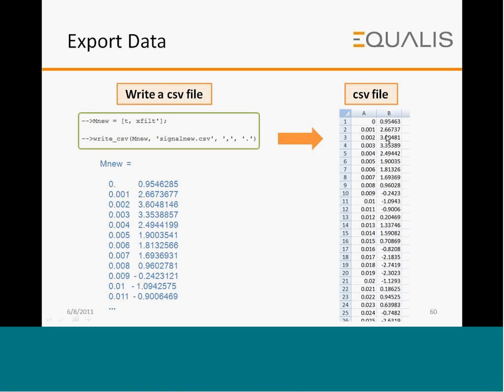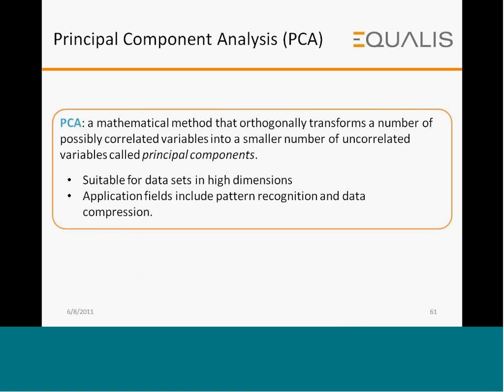Now I want to take it back to Excel. So to recap, we started with an Excel file, which was a CSV file. We read it in Scilab. Then we used the FIR filter. We plotted it. We plotted the FFT of the signal. We did some filtering. We constructed a filter in Scilab. Then we have a denoised signal which we bring back to Excel. So using Excel and Scilab, you can harness the functions of Scilab and do a lot, in a very productive way.